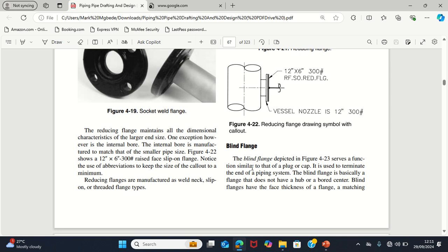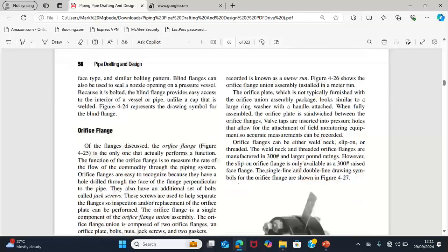That line that they use a blind flange to end may continue in the future, or there is a plan for an extension that they have to connect that line to in the nearest future. So that's why they use a blind flange.